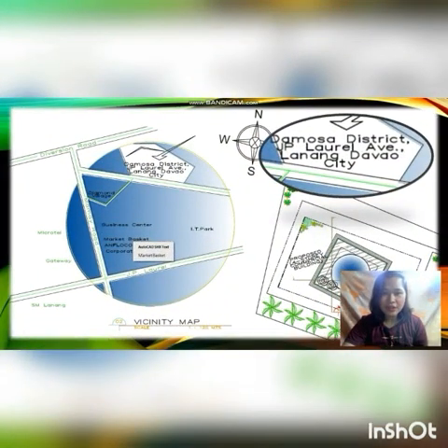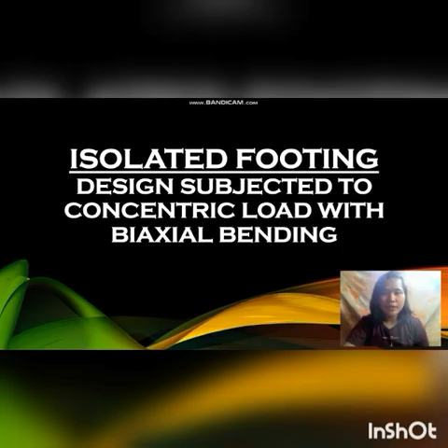Next, you can see here the location of our building. It is located at the Mosa District, JP Laurel Avenue, Lanang, Davao City. Our isolated footing design is subjected to concentric load with biaxial bending. So why do we use biaxial bending? Because we have two moments here, the MX and the MY, and the concentrated load PY.